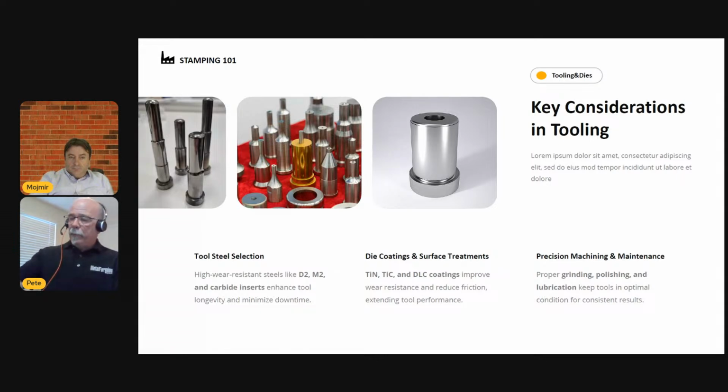One of the things with this punch that was going on was the grinding for resharpening was very aggressive. And they were moving a lot of material at one time to sharpen the punches. One, because they were over entering the punch into the die matrix way too far. So they were entering like an eighth of an inch.